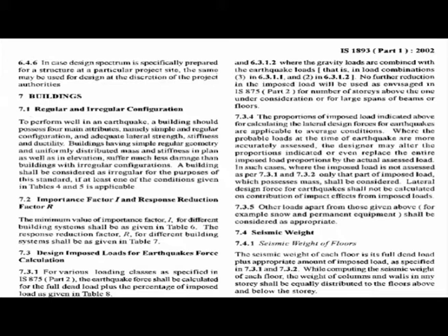So now let us come back here, because this is the basic thing we do. That means here we have dead load and imposed load, and due to that we have to find out the vertical load, and from there we can find out the effect laterally, how much lateral load you will consider, that is your earthquake load.